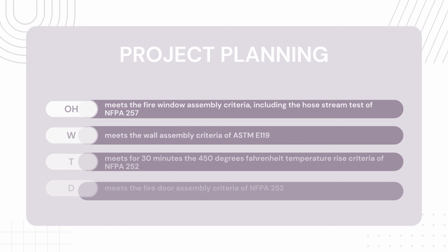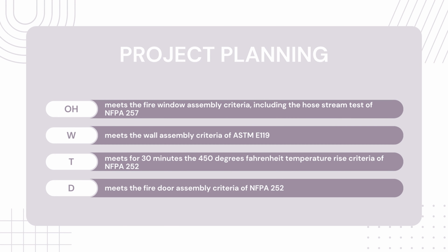OH meets the fire window assembly criteria, including the hose stream test of NFPA 257. W meets the wall assembly criteria of ASTM E119. T meets for 30 minutes the 450 degree Fahrenheit temperature rise criteria of NFPA 252. D meets the fire door assembly criteria of NFPA 252.